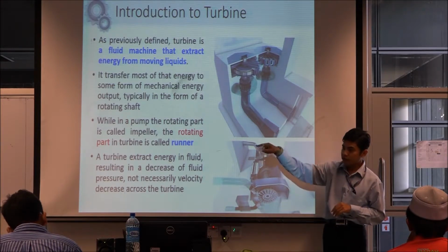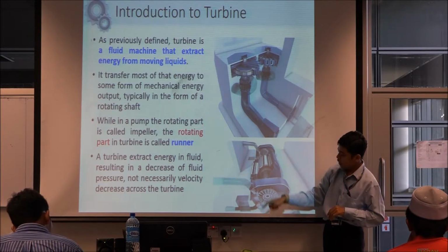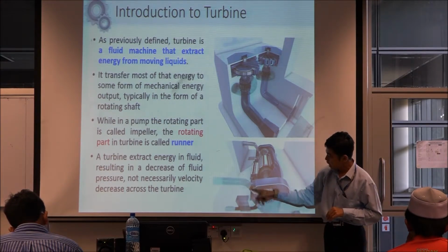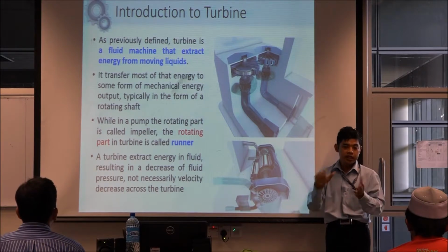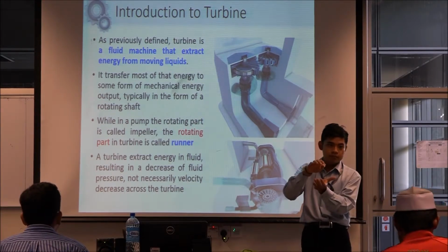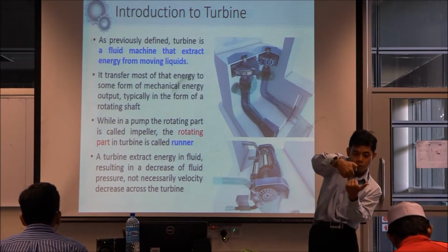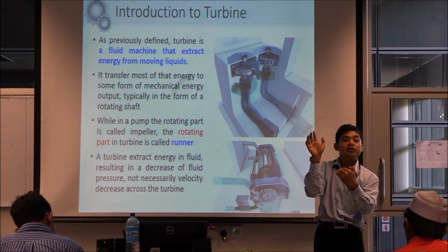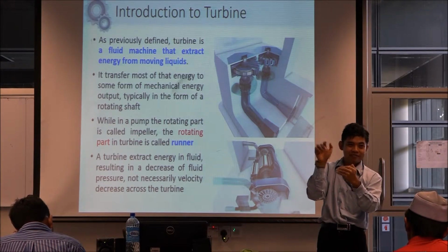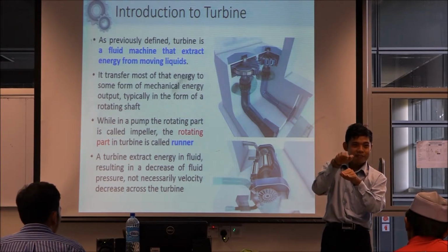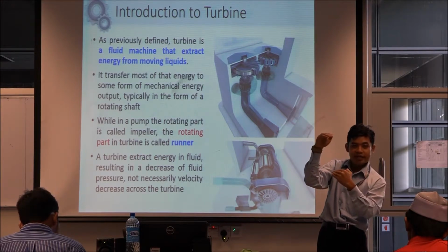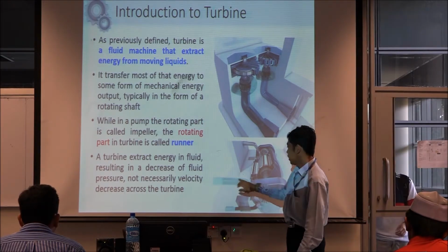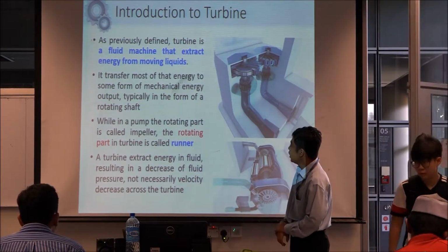The only difference with the one we have there, the one we have in the lab having one nozzle, right? But in this case, it has a few nozzles. The reason is to make the vibration minimum. Because if you have one side hit by the water, and you know the water is not as smooth as you think, right? The jet is kind of vibrating. So if you do that, you get a lot of vibration problems. That's why sometimes you get two like that. Okay?